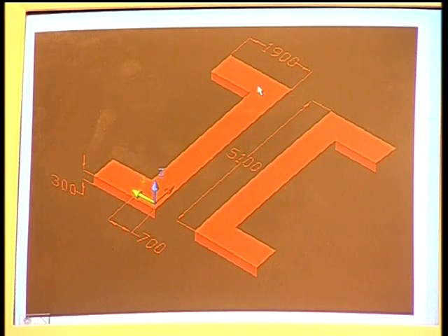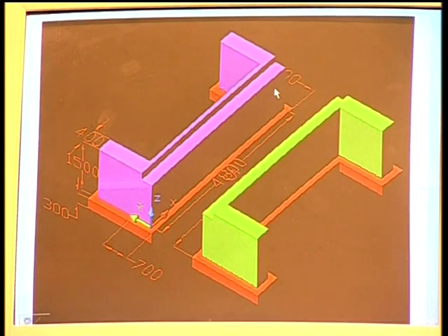Now, this is the bottom plane or bottom view of the foundation. Now, over this you can see here, this is the abutment. On either side you will have two abutments, and this is again return. So, this is your CC bed below the abutments. Now, here you can see this one is a return or wing wall, we call it. Here also you will have, so totally 2 on this side, another 2 on the other side, and you have two abutments.